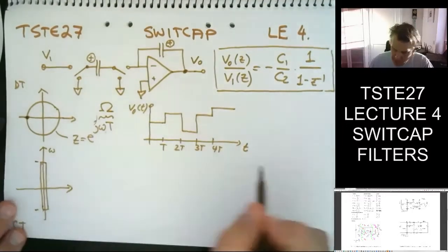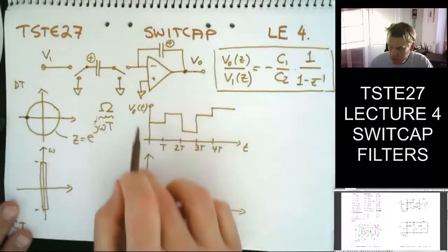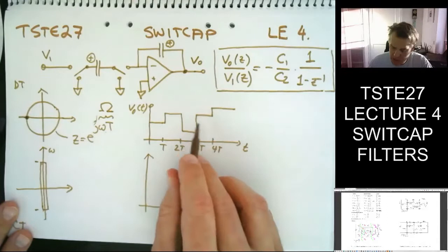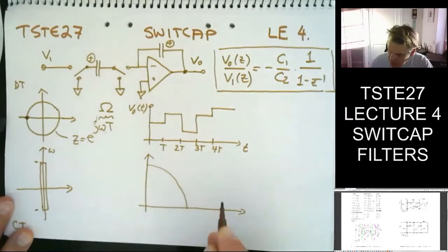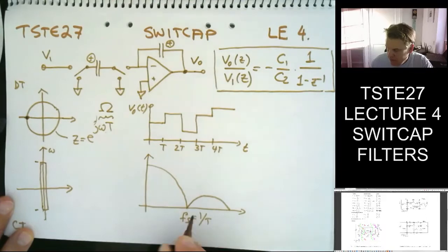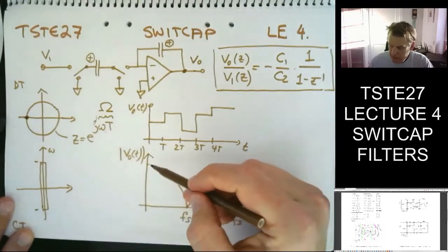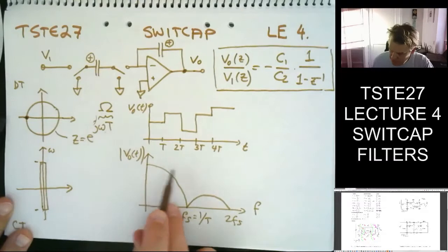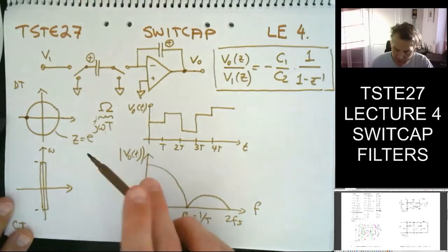And if I would look in the frequency domain, we said last time, if I would take the continuous time frequency spectrum of this type of signal, I would typically have the sinc-weighted structure, which has zeros at multiples of the sample frequency. And if we look at the structure here, we concluded that there is a certain frequency range where it makes sense to represent your signal.